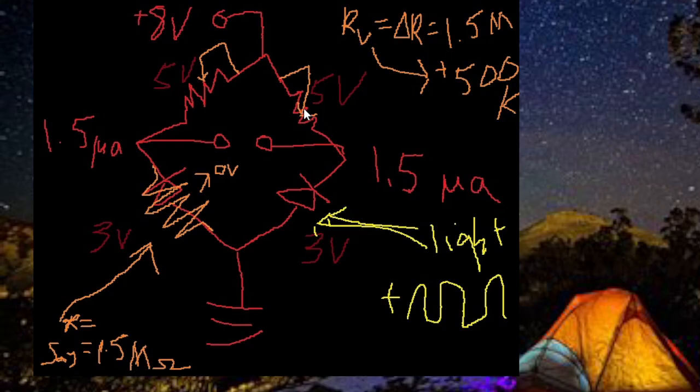I don't really know, because then we've got to put voltage on the other side. So what's going to happen when the voltages equal each other on both sides? There will be a split current flow on both sides that go to ground, and there will be no voltage drop across those two dots inside the Wheatstone bridge.